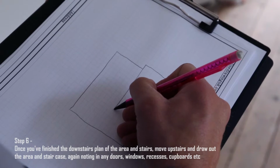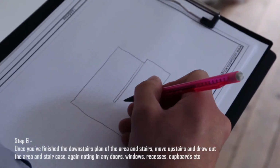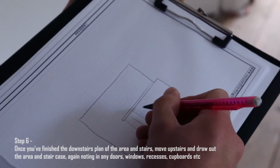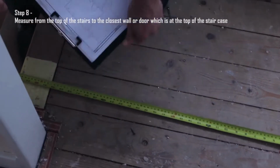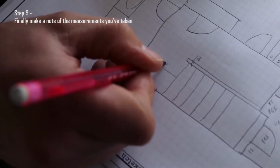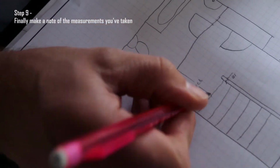When we go upstairs, it's all the same principles again in reverse. Draw out the stairs. We need a starting point and to the bulkhead and a width of balustrading. Just like we got the start of the stairs on the ground floor, we need the end of the stairs on the first floor, so we can determine by division the number of goings there are.